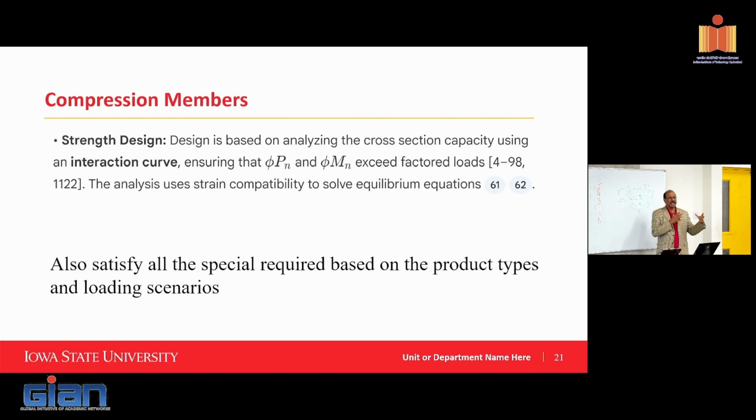So the precast side of things is not anything new, but understanding the sequence, identifying the potential scenarios, and applying the structural engineering knowledge, the concrete knowledge, and the pre-stressing knowledge makes sure that you don't create a situation where the beam can fail, crack, or deflect more permanently, things of that nature. That's what you want to prevent. Any questions?